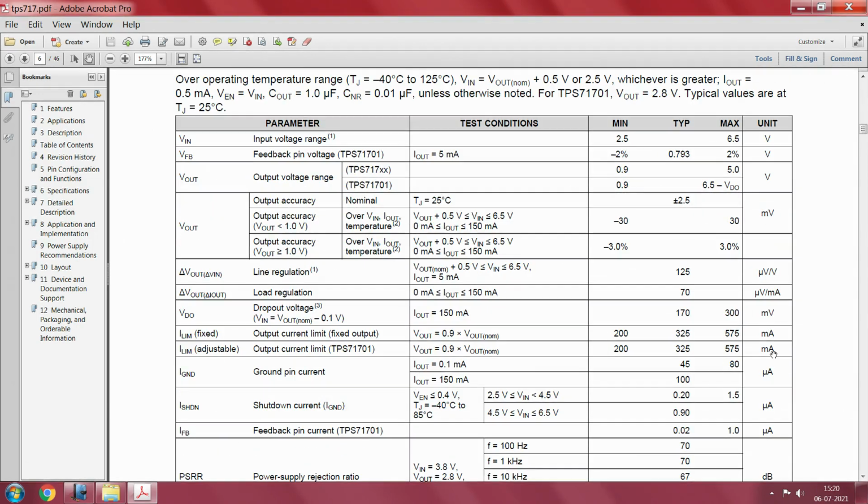Then you have electrical parameters, and very interesting parameters, particularly you may want to look at the things that we sort of know. One of the things we know is about the accuracy. This is a very important aspect where he talks about nominal output accuracy, then over V in, V out, temperature, and over V in, V out, temperature 1 and temperature 2 for 2 different temperatures.